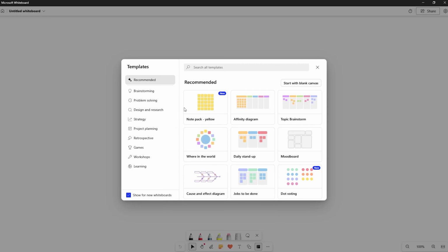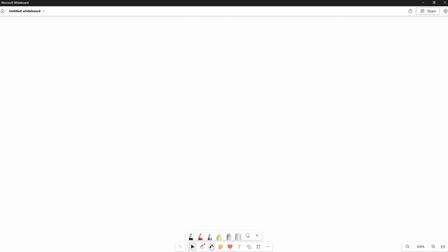The example says the mold is a 48 cavity mold, and it is supposed to run at a 4 second cycle time, and 10,000 parts is the average scrap produced in a day. Average cycling hours is 22.5 out of 24 hours of available time, and the expected cycle time is 3.8 seconds. So it asks us to calculate the total equipment productivity.